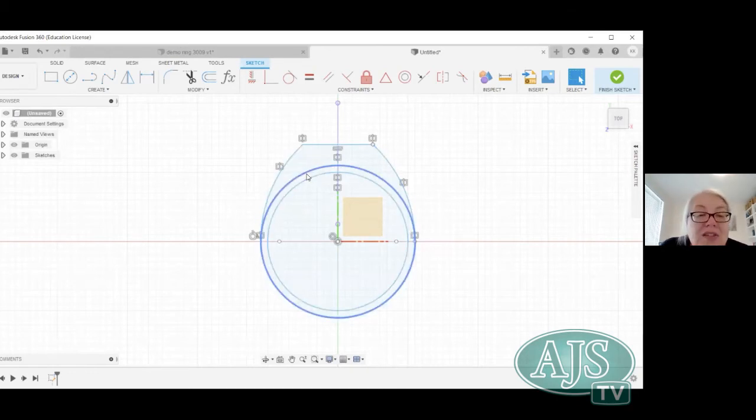Now, we also know that we don't want this to be solid silver when we make it, or metal. I mean, you can if you want it to be a really big chunky bugger, but remember that the bigger these top surfaces are, the more likely it is to want to try and rotate, and the harder it is to wear. So often we want to hollow out that interior surface. This is where our offset tool comes in handy again.